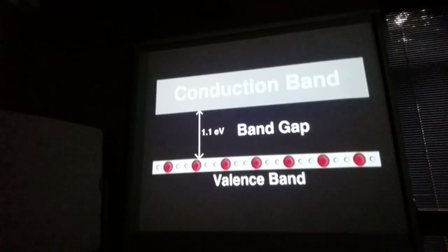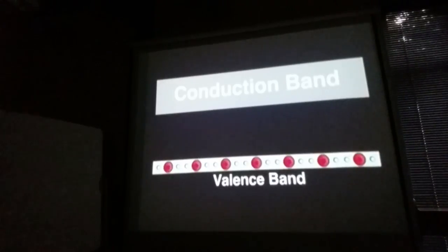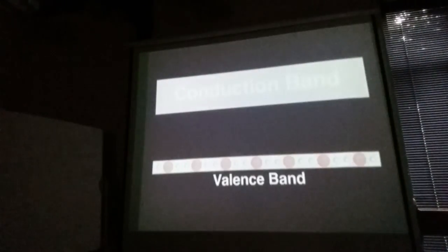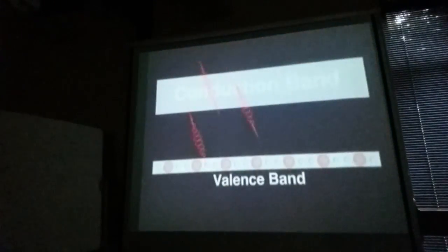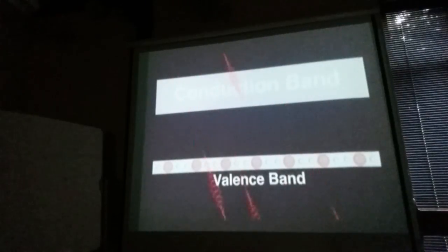The band gap refers to an energy interval where no electron is stable. Since the silicon atoms in the crystal are electrically neutral, we will indicate this neutrality by graying them out. Now, let's shine a light on our silicon crystal. If the incoming photon's energy is insufficient, the electron will stay in the valence band. However, if a photon of light has sufficient energy, a valence electron can absorb that photon, jumping up into the conduction band.